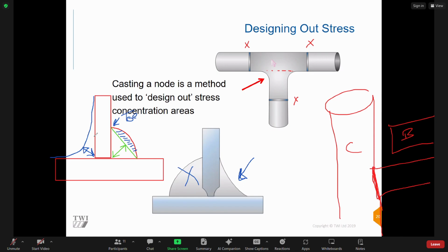Okay, so again, there's always a trade-off between best fatigue properties and the cost. So ideally we want a mitre fillet weld, which is the best compromise. Okay, but again, we'll talk more on welding that Wednesday.